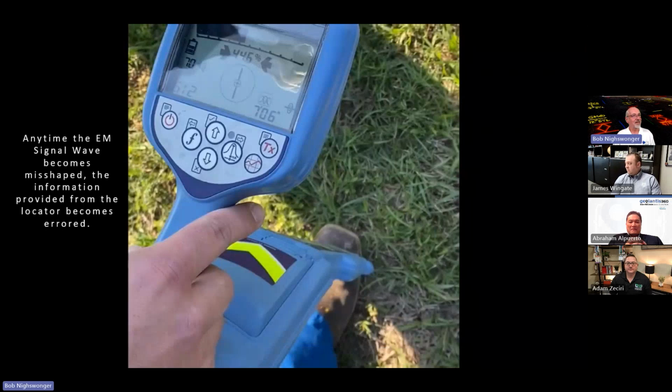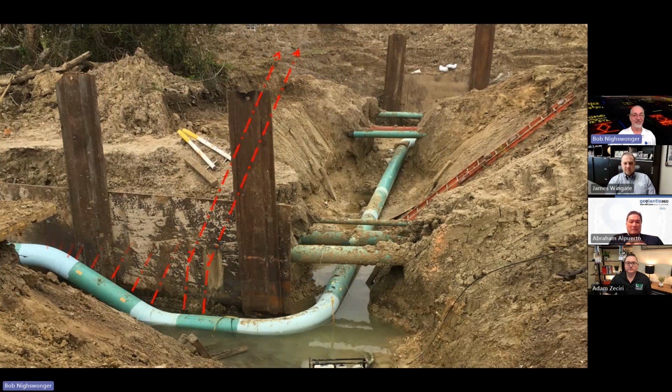So setting up bore plans, I'm going to go ahead and set this drill to go 12 feet deep. I've got a map of every line in the road that says the deepest one there is 8 feet. We don't want them to have too much confidence in what we're providing. And that's a location of the top dead center of a signal, not the actual precise location of the line.